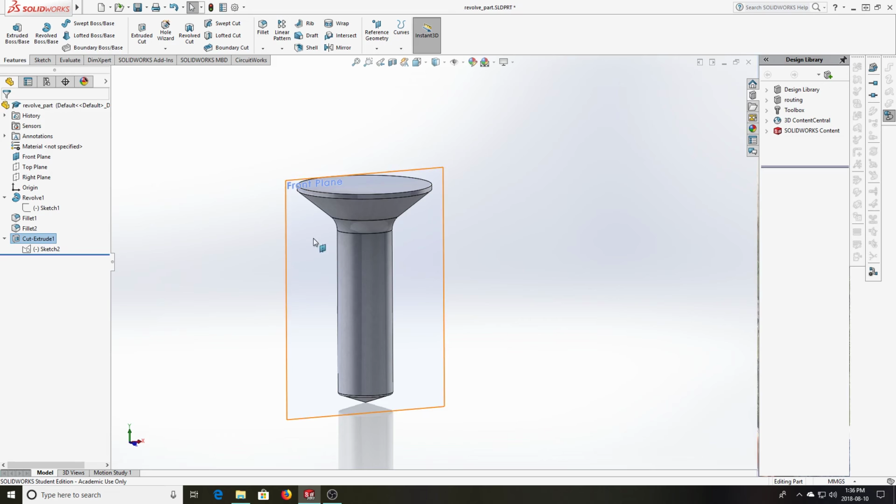Now that's showing you three different ways to do the same thing in this case. One was using a fillet, one was using an edit to the original sketch, and one was using another cut axially with the part. When you're modeling things in SolidWorks, there are always multiple ways you could get at something. Some ways are easier to understand and to implement, some ways are harder, but it's worth knowing how many options you have in this.